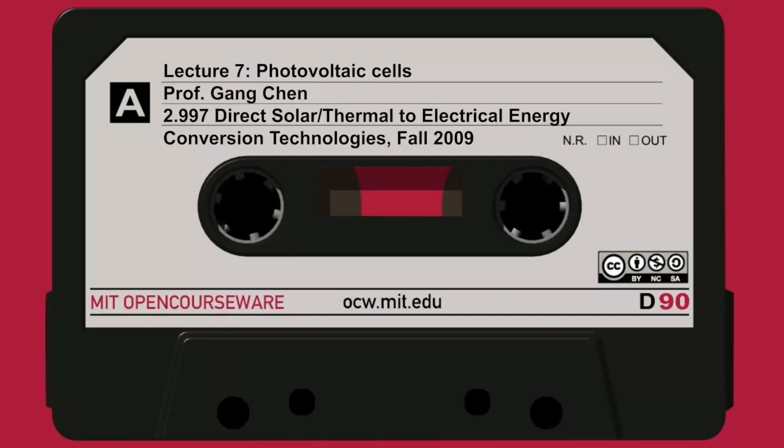it lifts one electron from the valence band to the conduction band. Right? And this could happen anywhere in the device. That depends on where the photon is absorbed; we'll talk about that later. So what I'm drawing, if my photon happens to be absorbed within the space charge region, then the electron-hole pair is generated within the space charge region. Now, what happens after this generation?